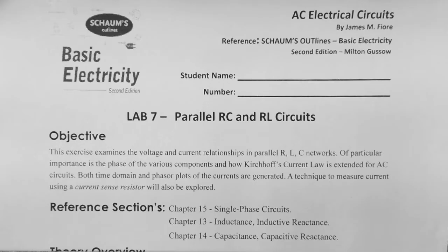It says of particular importance is the phase of the various components and how Kirchhoff's current law is extended for AC circuits. So we're going to draw both time domain and phasor plots of the currents, and we're going to use a special technique to measure the current. We're going to be using current sensing resistors, so these will be explored further in the lab.